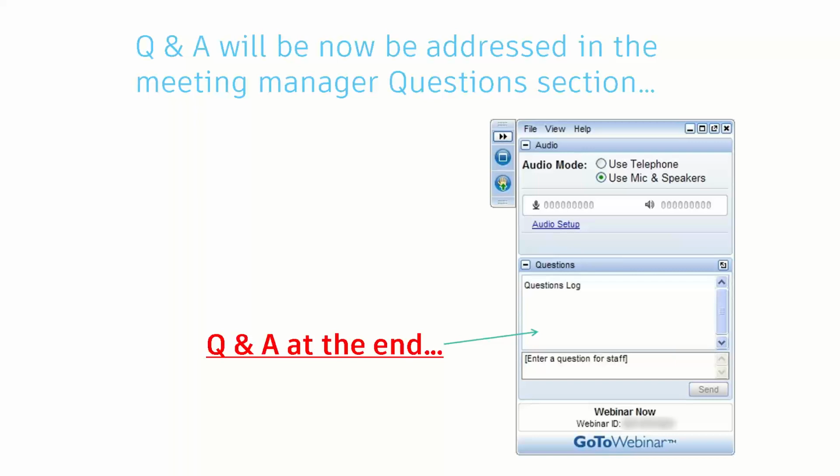Yeah, that's a tricky one. Converting all of them at once, no. There's no easy button way of doing that, especially if they have issues. If you're bringing in a STEP file that's already a surface via the import into an assembly, there is a way to convert that into a single surface, and then you can thicken it. But again, if it's got any issues, then you're going to have to go back to the single bodies and start working from there.